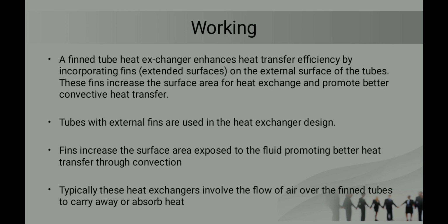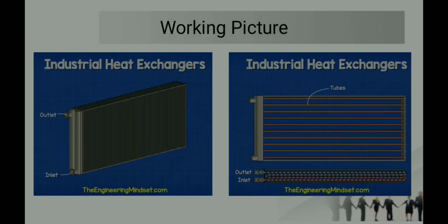So let us see the working in depth with pictures of the fin tube heat exchanger. First, it is a picture of a fin tube heat exchanger. We have an inlet and an outlet in the same direction, where the inlet is at the bottom and the outlet is at the top. In the next picture, we can see a tube flowing through a hairpin-like structure.